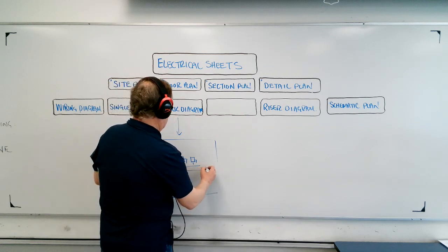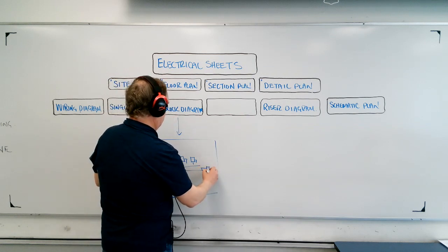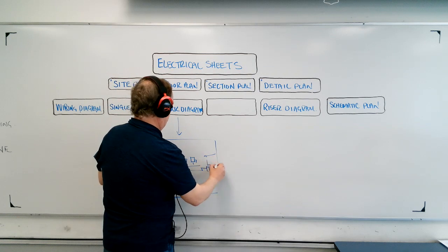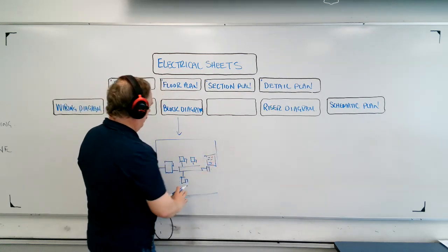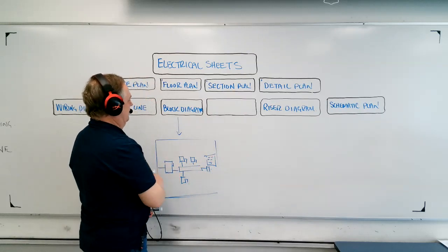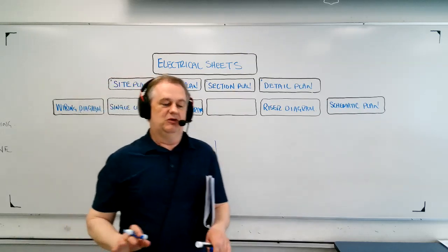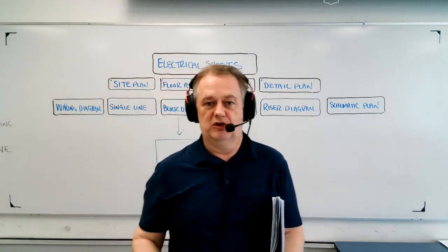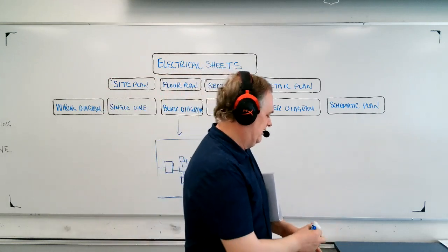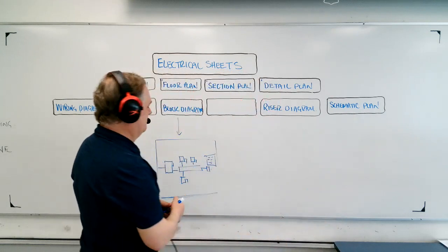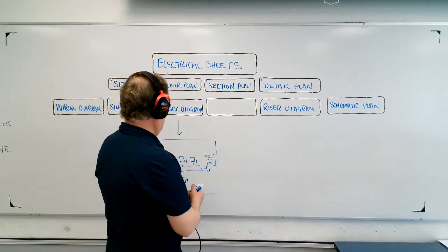And this one is going to go disconnect, and then there's going to be a panel here, okay? And it'll actually physically show you the layout on the wall, okay? So this is an actual layout. So a block diagram, particularly in electrical rooms, MCCs, will show physically where all the parts and pieces are going to be placed and how they're going to fit together.